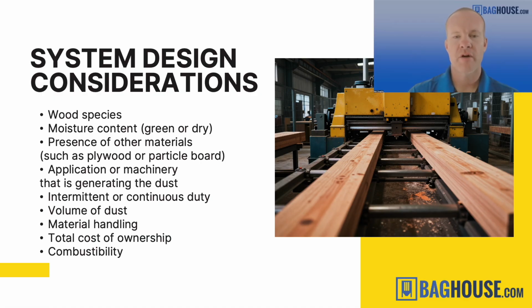Presence of other materials, plywood and particle board. I would say even more important would be nails and staples and things like that. If they have a potential to make their way into your dust collection system, it's very important that we know that up front when we go to design the dust collection system.